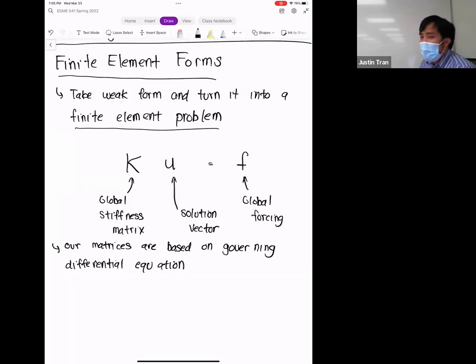And remember, that's really the power of finite elements. Finite elements, as a method, has its power in taking a very complicated partial differential equation. In our cases, we're just doing ODEs, and it gives us a way to solve for its solution without actually having to solve the differential equation. The approach here is fundamentally different because we're not just doing it for very specific structural elements. We're doing these based on the equation.